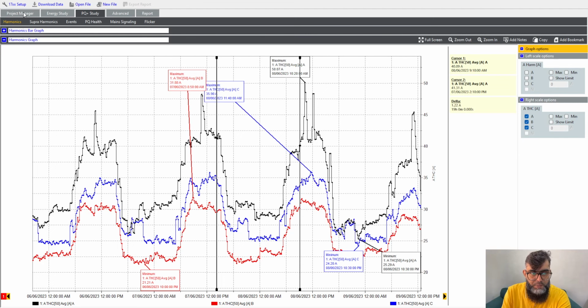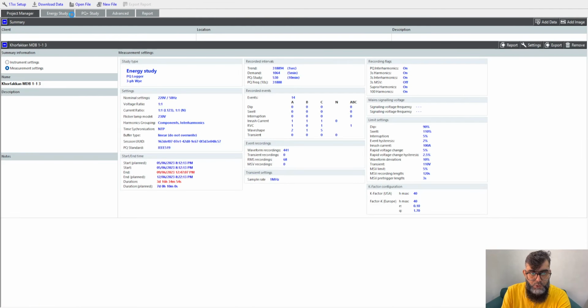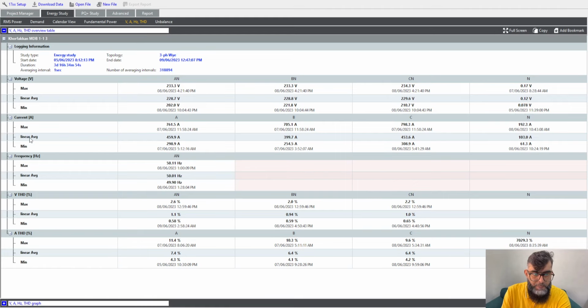And if I calculate the percentage based on 50 amps and the linear average of 450, then my percentages go significantly higher, right? And if I calculate it on 800 amps, which the power quality analyzer has recorded, and this is probably the peak value, still my percentage will be significantly higher as compared to 2500.